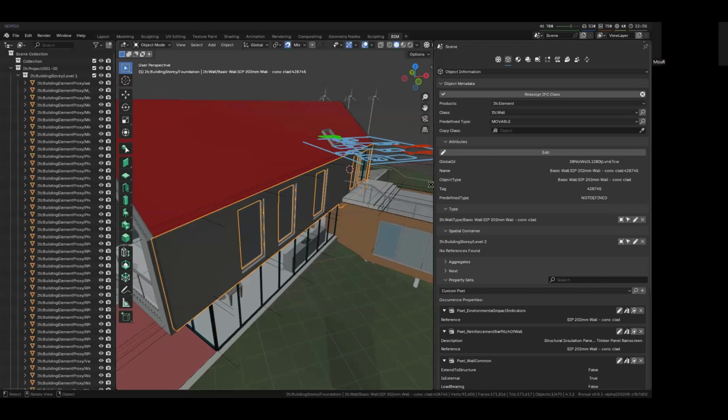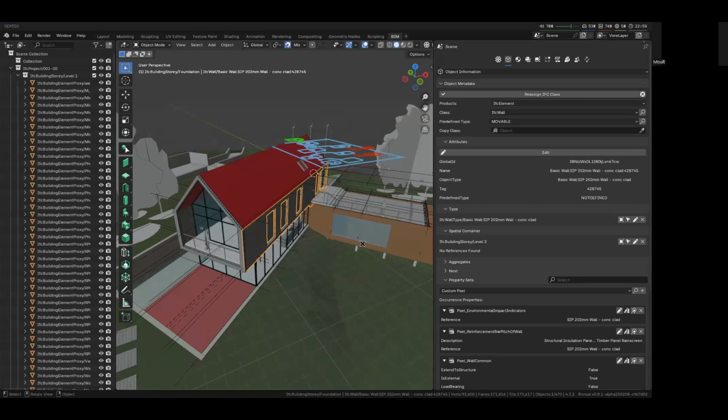So I guess that's what I'd recommend to everybody. Classify everything 2 levels deep. If you are in control of any sort of requirements, specify all your requirements in terms of IFC classes, and that will save you a lot of heartache. Never, ever say, I want these 15 bits of data across everything, because that doesn't make any sense. Always put it in terms of IFC objects. So later on, if you ever write an IDS, IDS is also very well integrated into IFC classes. It's a first class facet in there.